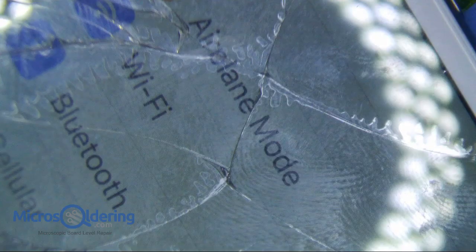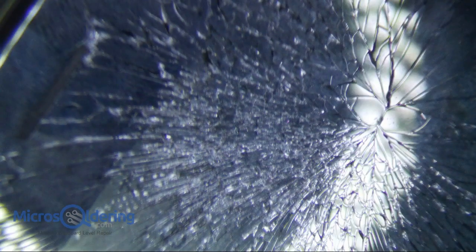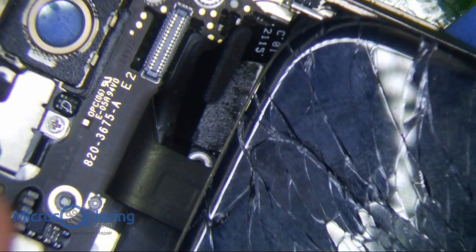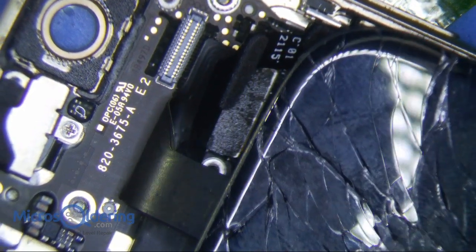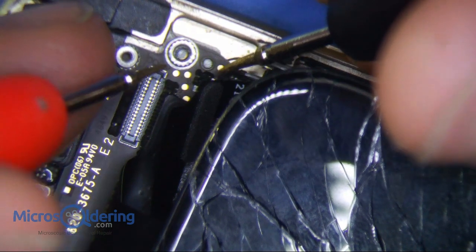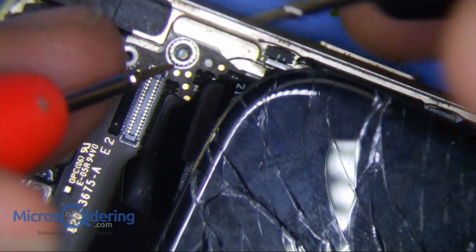Well, all right. So we're going to go to the phones now, under my scope here. So the screen is on. I just changed the setting to never disable. The screen has to be on in order for you to test the backlight voltages. Well, it technically doesn't have to be on, but it has to be connected when you boot up in order for the boosted voltages to appear, because, well, I'm not going to get into that right now. All right, so these are the two test points we have. This is the anode connection, this is the other anode connection of the two. So basically, these are the two outputs of the backlight system, okay?